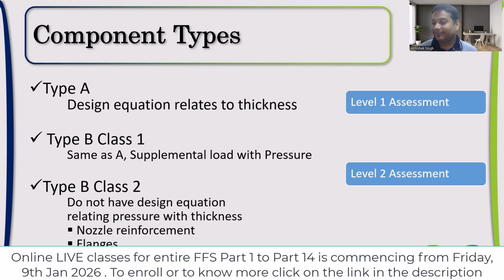Where does the roof of the tank fail? A very general question. It may fail at multiple locations depending upon the type you have. First of all, the type may also be multiple. If you're talking about cone type roofs and you apply a local load, it may fail because of that. If it is self-supported, even the cone type may have multiple types: self-supported, girder and rafter supported, or column type. So all the different types will fail differently.